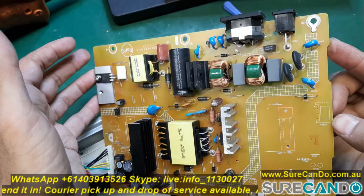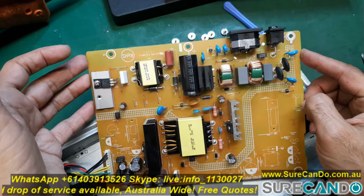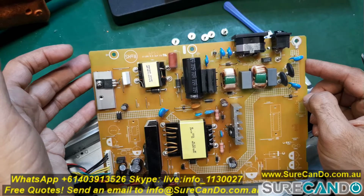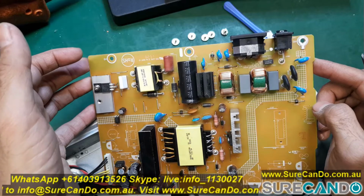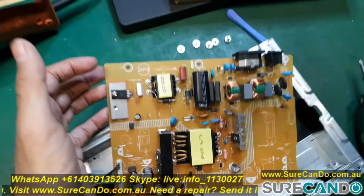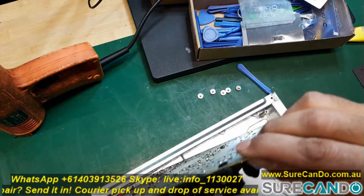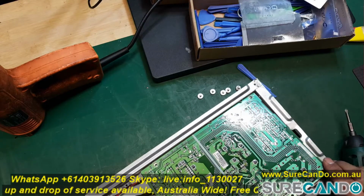I didn't test any of the components with the multimeter, as I didn't think I needed to, because the unit was not turning off or flickering or any of those power related issues. The backlight was staying on, if you remember, just no picture. So to me that tells me it's an integrated component, like an IC chip on the G-Sync module, the actual picture controller, which is the one on the left of this. So let's put this guy back and have a look at the main controller.